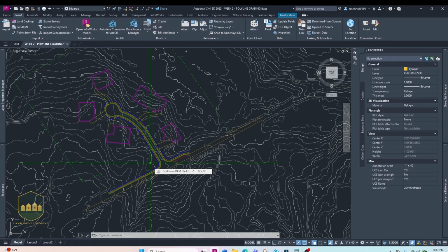And maybe throughout the years, you'll eventually get it. But I think it'll be a lot quicker for you to first start doing polyline grading, develop that intuitive sense of how the contour is supposed to look, and then start using automation tools. And that is truly how you become a great engineer, because there's plenty of people out there who can just press buttons and see something happen on CAD. What truly is going to make you different is the ability to check the computer, to check, hey, are these automation tools correct? Because even though the automation tools are pretty good, they're flawed.